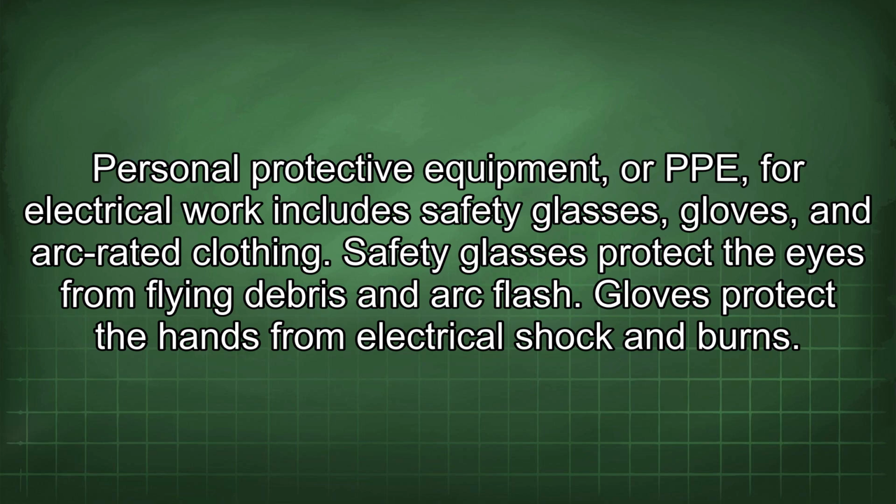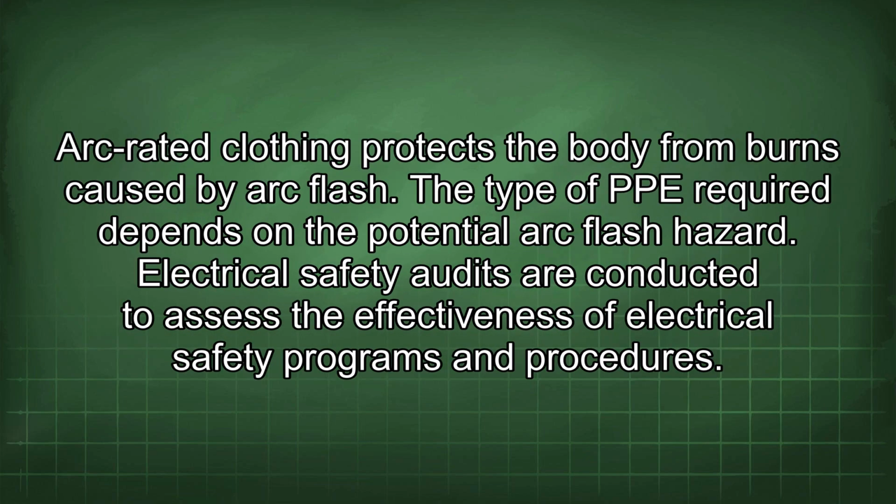Safety glasses protect the eyes from flying debris and arc flash. Gloves protect the hands from electrical shock and burns. Arc-rated clothing protects the body from burns caused by arc flash. The type of PPE required depends on the potential arc flash hazard.